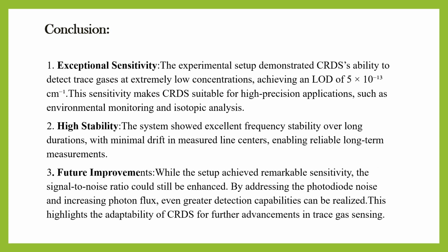Coming to conclusion. The conclusion includes that it shows exceptional sensitivity. The experimental setup demonstrated CRDS's ability to detect trace gases at extremely low concentrations, achieving an LOD of 5 × 10^-13 per centimeter.